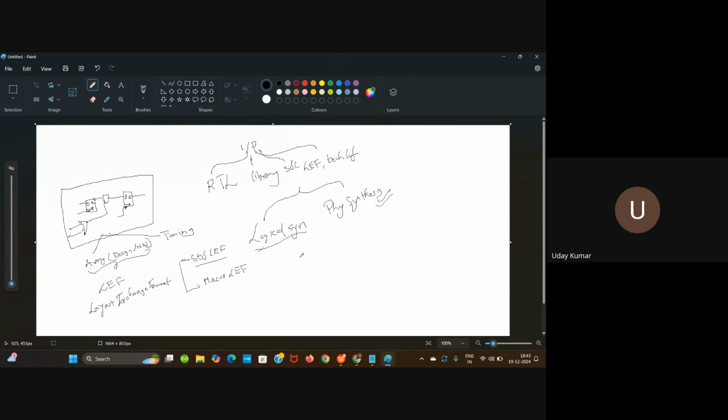In my experience, the standard cells I know are AND gate, OR gate, NAND, NOR, XOR. These are all the gates that will be designed by a standard cell layout engineer with the TSMC layout rules, and would be sold as an IP, as a bunch of packages to the physical design teams so that they would implement the physical design.